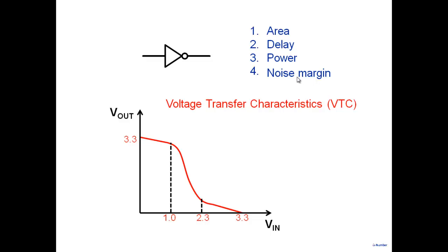Right? And where do we get this noise margin from? You're seeing that this is a property of my voltage transfer characteristics. Different voltage transfer characteristics will have different implications for noise margin, because we are talking about gain less than 1 here, gain less than 1 here, how the noise attenuates and all that. So all those things you get from the voltage transfer characteristics here.